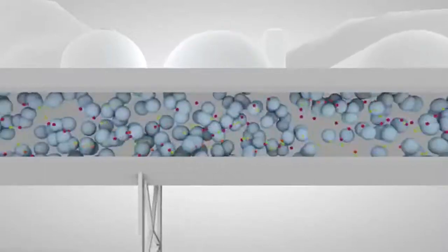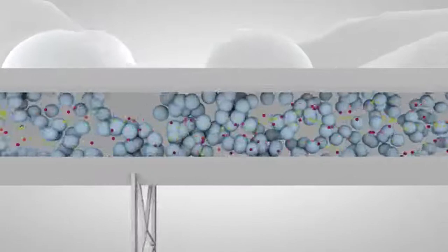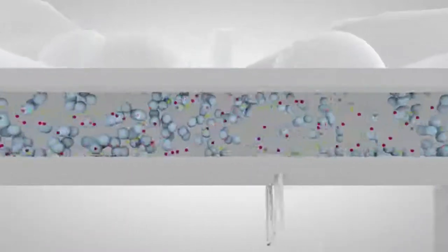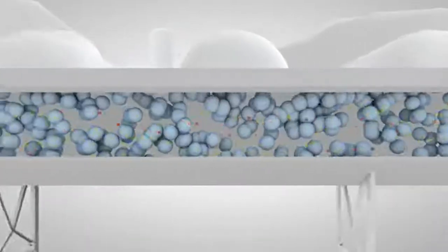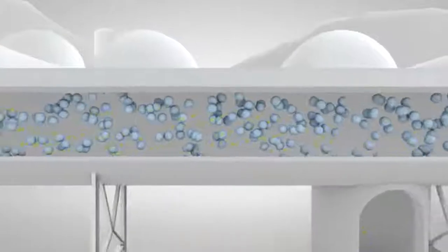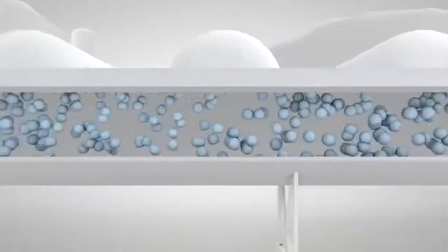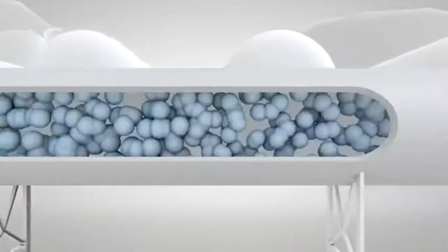Natural gas is mostly methane with varying amounts of other hydrocarbons and impurities that can freeze and foul equipment. We remove the impurities in the pre-treatment area of the LNG plant. Here we also remove heavy hydrocarbons, inert gases, and other gases that accompany the methane, that is, natural gas. Now we can begin to liquefy this clean gas.